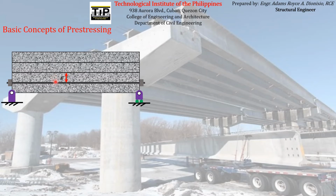So we usually locate pre-stressing reinforcement at a distance E from the centroid so that if a compressive force will be applied to the concrete due to that pre-stressing reinforcement, we will have a more acceptable total stress being experienced by the concrete beam. Actually, this type of pre-stressing, unlike the concentric pre-stressing, is called eccentric pre-stressing. So this is different from concentric pre-stressing. When we say concentric pre-stressing, the pre-stressing reinforcement is located along the centroid of the cross-sectional area of the concrete beam. But when we say eccentric pre-stressing, the pre-stressing reinforcement is located at a certain eccentricity or at a certain distance from the neutral axis or the neutral surface, which is this case, this illustration. This is eccentric pre-stressing.